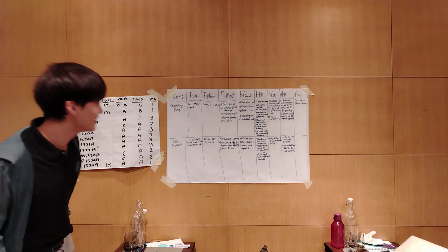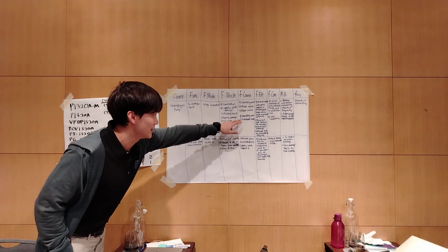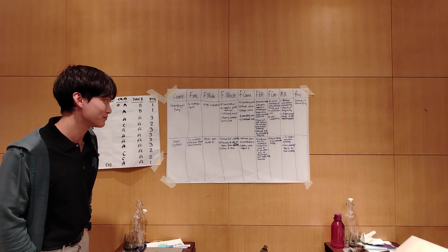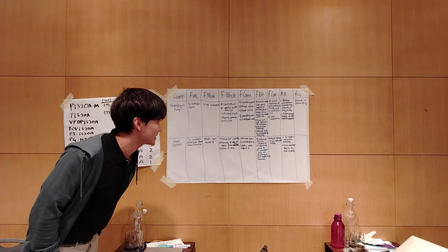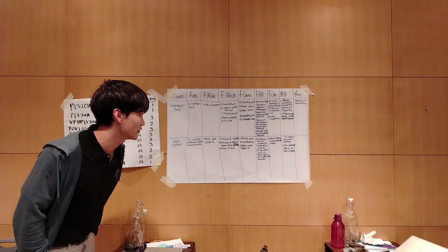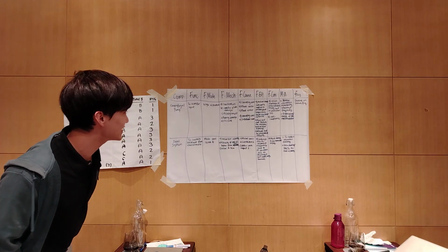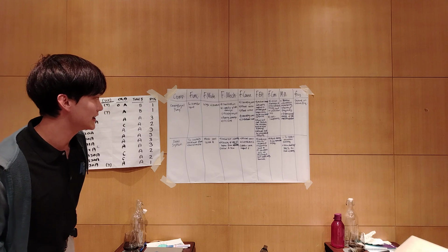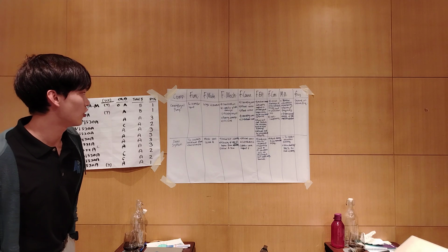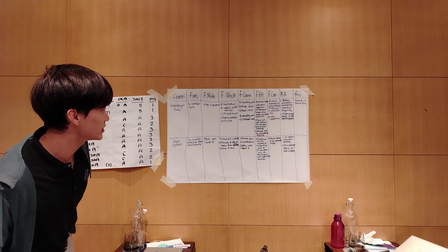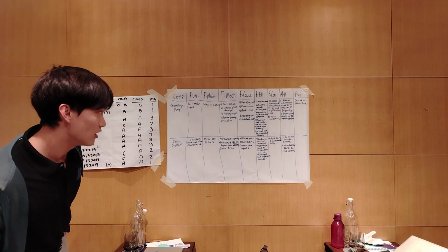Okay, so failure effect A: the medium cannot sufficiently supply to the processing plant, so this will trigger the LL alarm on our downstream equipment. B, pump seal failure rate increases, leading to asset damage. And C, oil leak leads to environment and integrity issues. So for consequences, we have asset damage, environmental safety issues leading to production loss, and also non-compliance to statutory law.